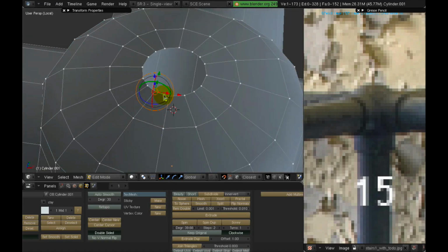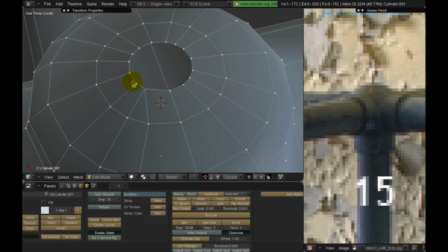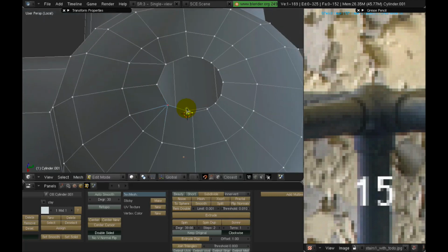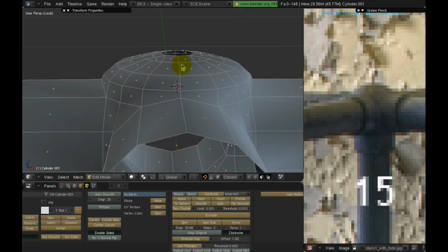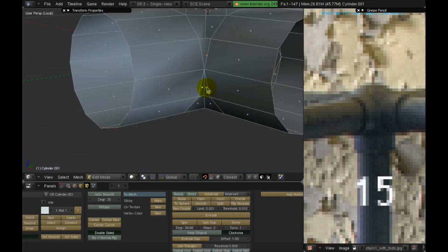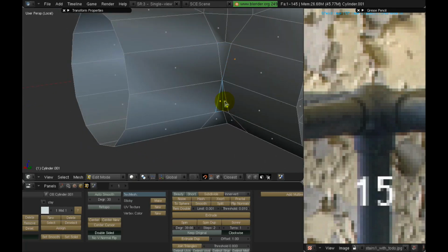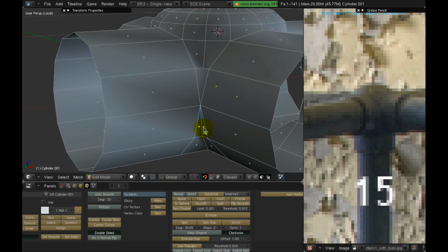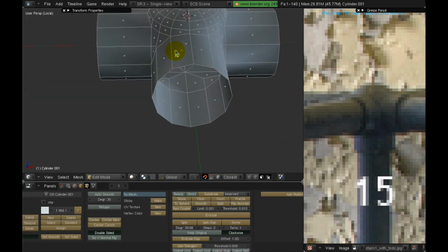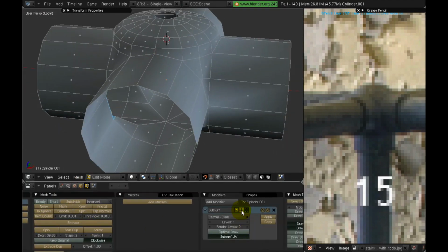And we can see at the top we have groupings of 3 vertices, and that's really quite a bit. So with auto merge turned on, we can snap these to create 2 pairs of triangles, and we select the pairs and press the F key to convert them to faces, to quads. And we'll do the same thing in the corners between each of the openings.